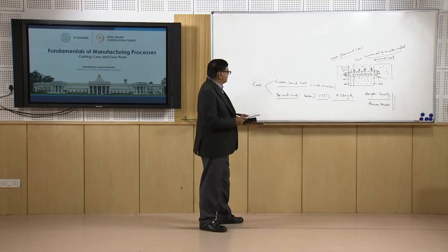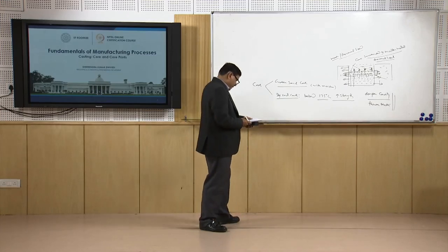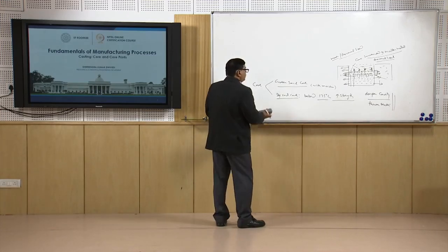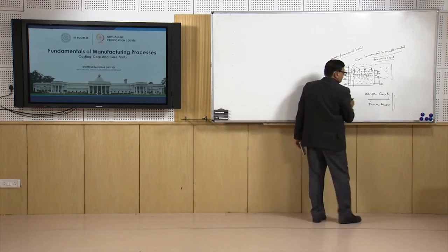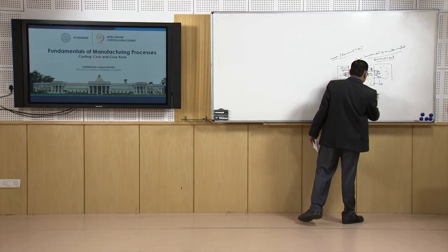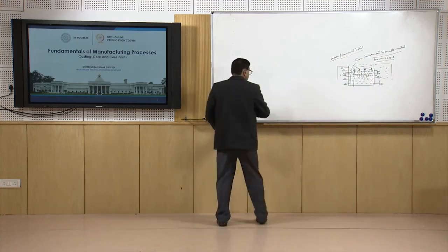Otherwise, the green sand core will break down if it is used for thinner sections and for deeper or high aspect ratio cavities.